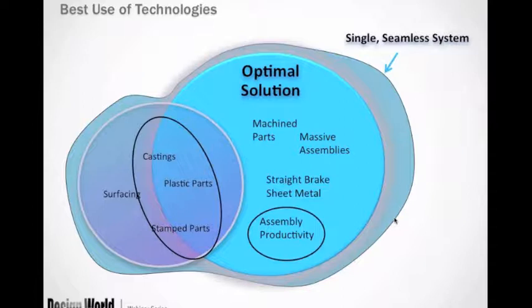And I would suggest that all that stuff can be done within this blue circle here. All be done parametrically, dimension-driven, but with no history tree, and be very productive without having all that regeneration and feature failure. But then that aspect that has to do with the manufacturing pieces of getting the draft angles just right and adding all the complicated rounding and the way they interact can be done in the history part of the system.